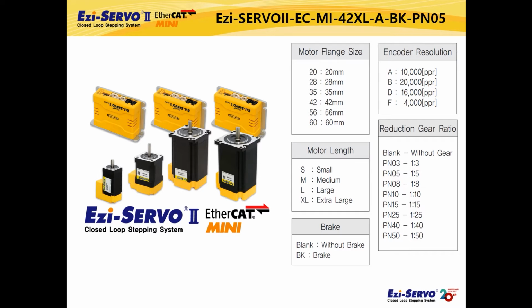Gearbox and brake specifications are also available. Gearboxes are planetary gearboxes, and gear ratio can be selected as shown in the table. The brake is a non-excitation type that activates when the power goes off. For example, you can use it to prevent the Z-axis load from falling. Please refer to the catalog for details.